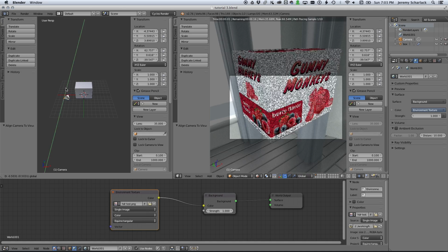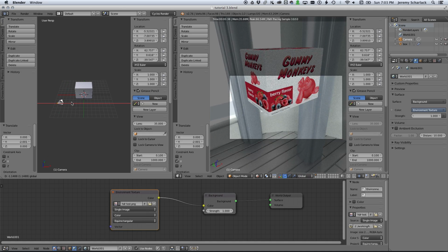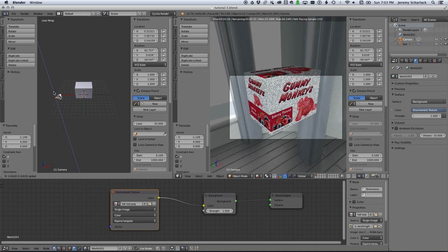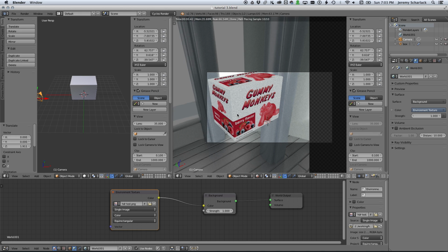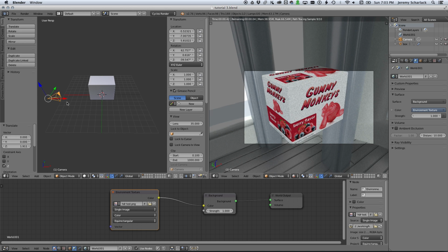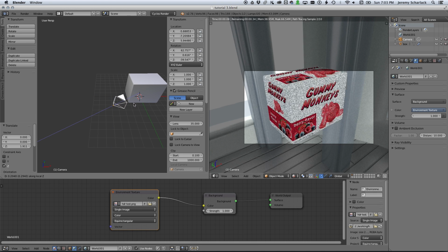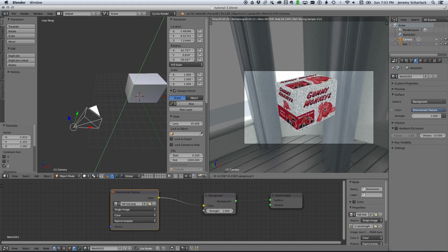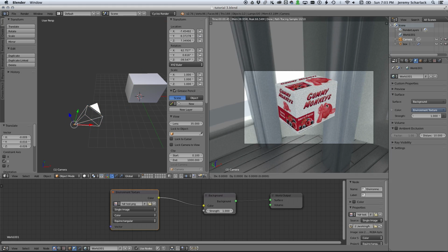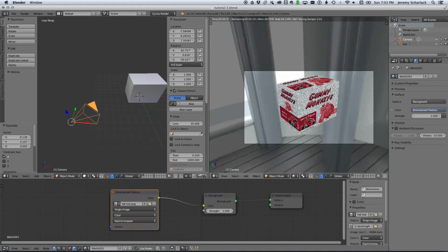So we can move it back in these directions. But another easier way to do it is to move it on what's called the camera's own axes. The z-axis of the camera is actually facing downward. So I'm going to get rid of these edges here. I can hit G, Z, Z, and then that just dollies out. Then I can go G, Y, Y, and that moves me up and down. G, X, X, left and right.